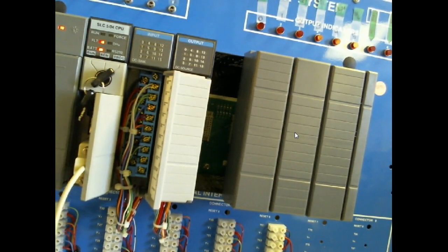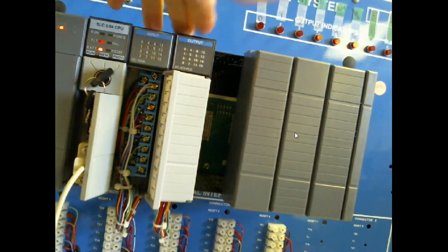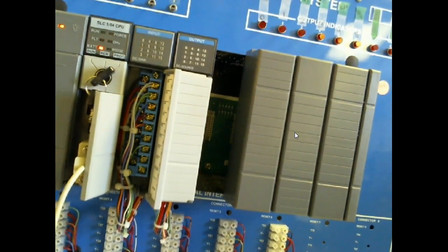So when you address a module, you have to specify which slot numbers. So we won't use slot 0. We'll start with slot 1, right? You understand? Because we don't address the CPU, but the CPU's got to address the module. Slot 1 from the input, slot 2 for output. Yeah, on this one, I could swap these around if they wasn't all tied down. It's up to you to determine what you use in the slot.